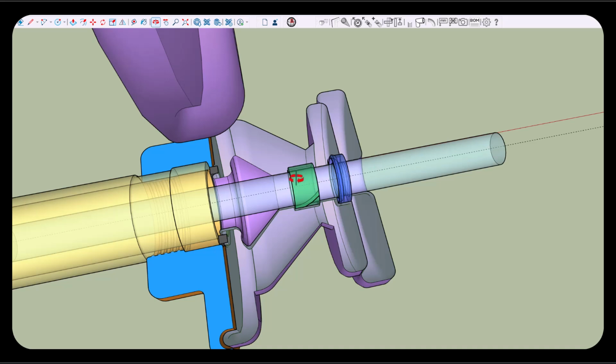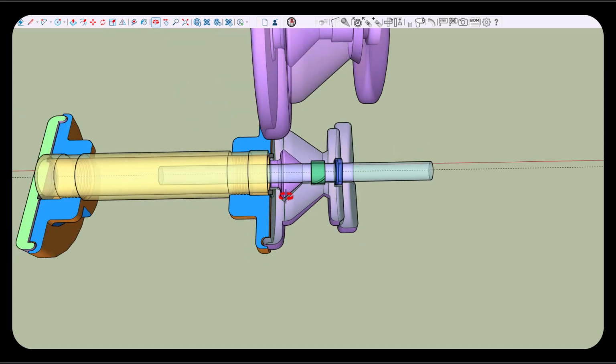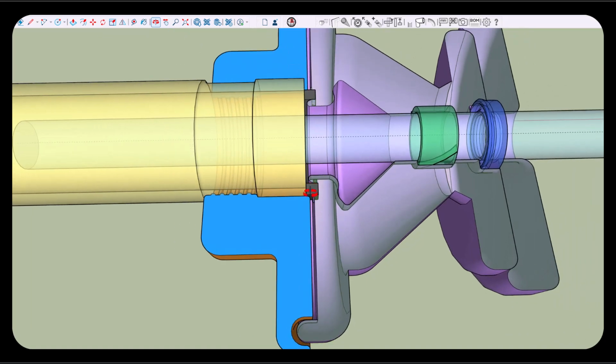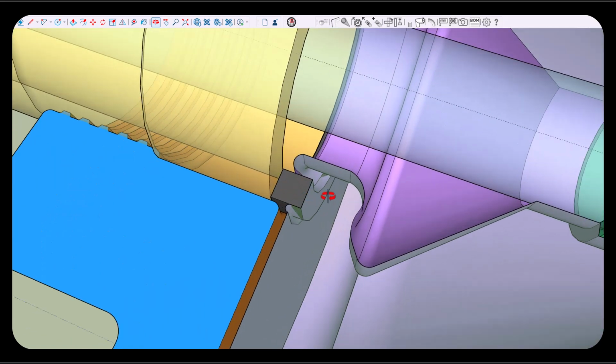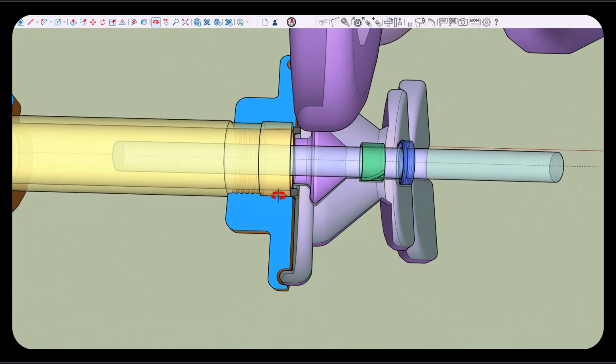And then this is the 1/2-inch shaft, and this is squeezed tight by those bolts. See how this shapes around so it'll hold this square cross-section O-ring, and this purple piece is being pushed up against this part of the square cross-section O-ring, and the Delrin tube is being pushed against the other side of it. So that should seal it.